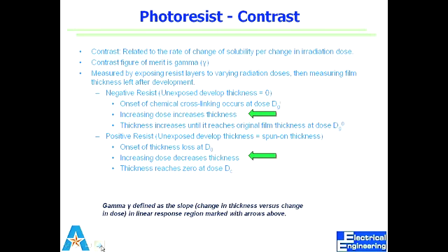So the behavior of the resist during the chemical change defines what kind of features, how small of a feature we can get out of the same thickness, same dose. The only difference is one is negative resist, the other is positive resist.